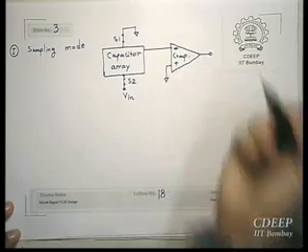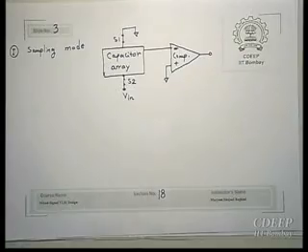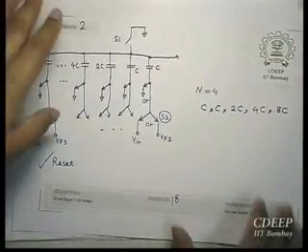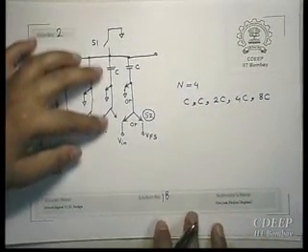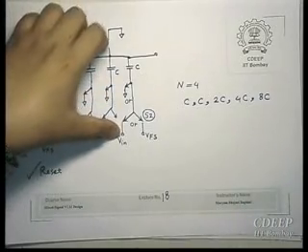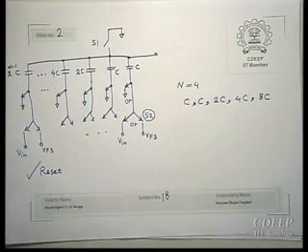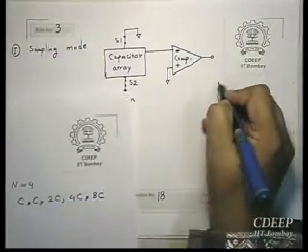This is comparator. So what it does means that when you come back here, what we want is to sample the input. Therefore, it is obvious that we have to connect the upper plate, for example, to ground, and the lower plate to Vin. Now, all capacitors will have Vin on them, right? Therefore, all capacitors will have Vin in this way.